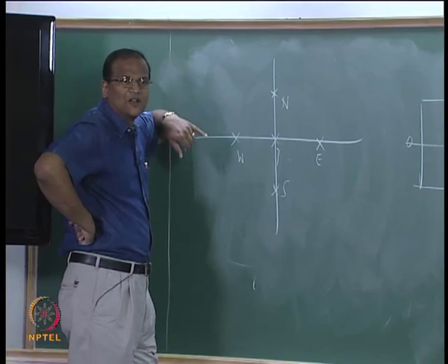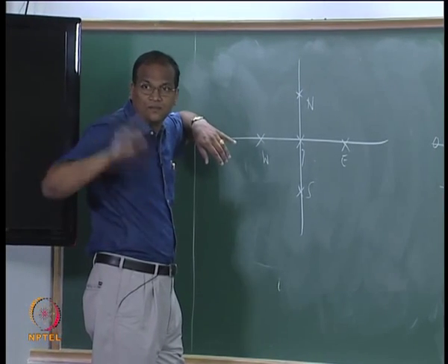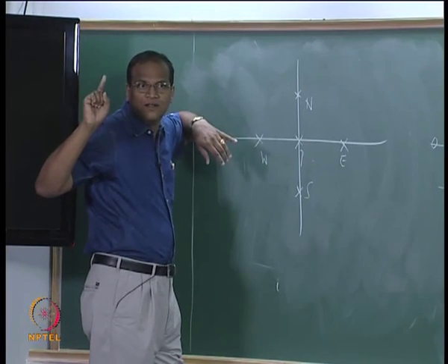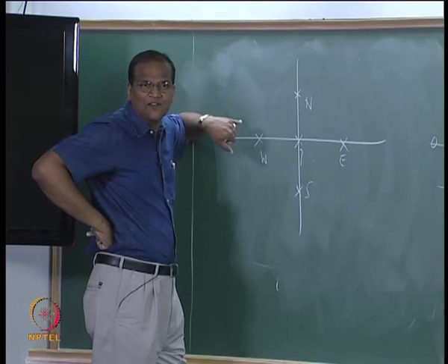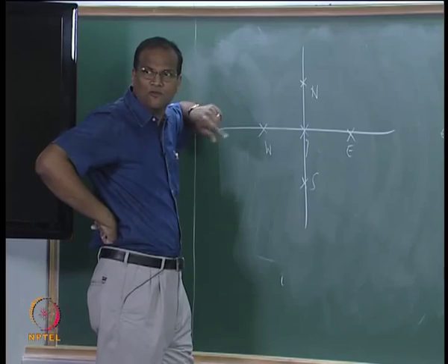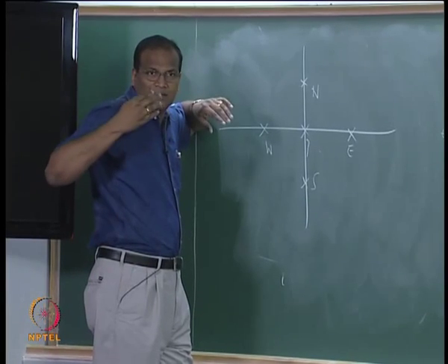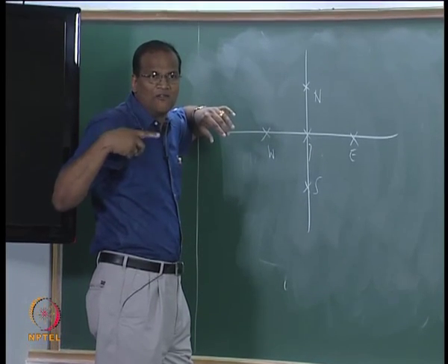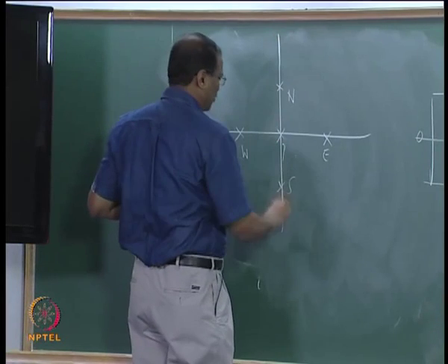What I have done essentially is what is called a 5-point stencil. In computational heat transfer or CFD, they will say it is a 5-point stencil. That means the value of the node is dependent on 4 neighbors. That node itself plus 4 others is called a 5-point stencil. You can have a higher order scheme.